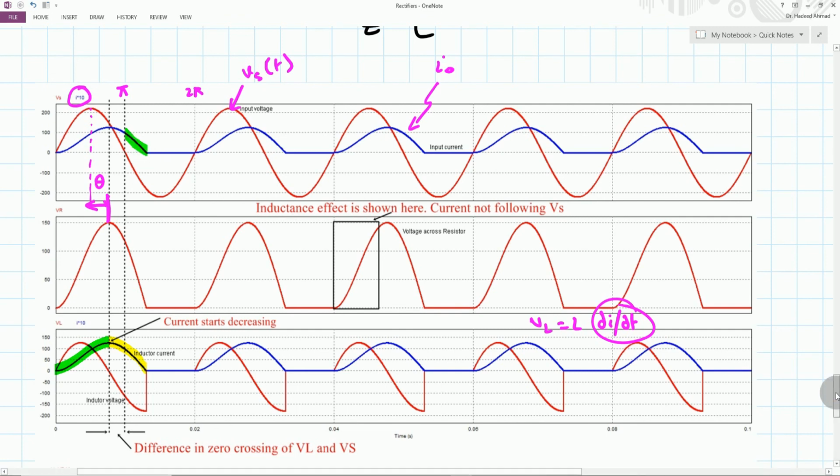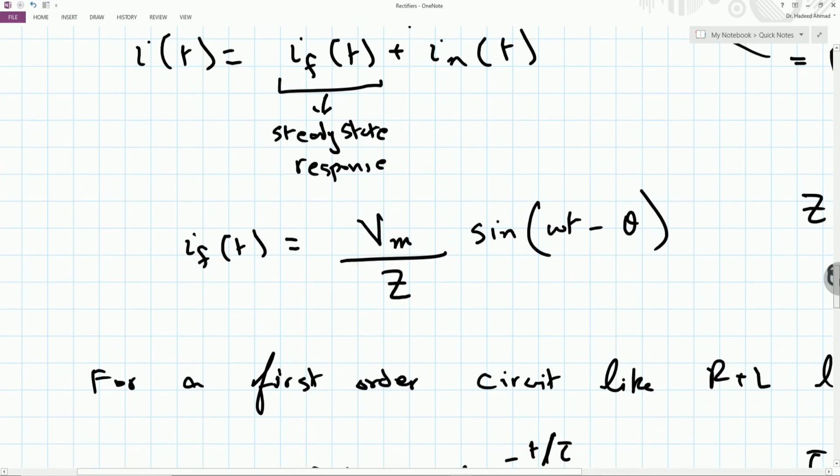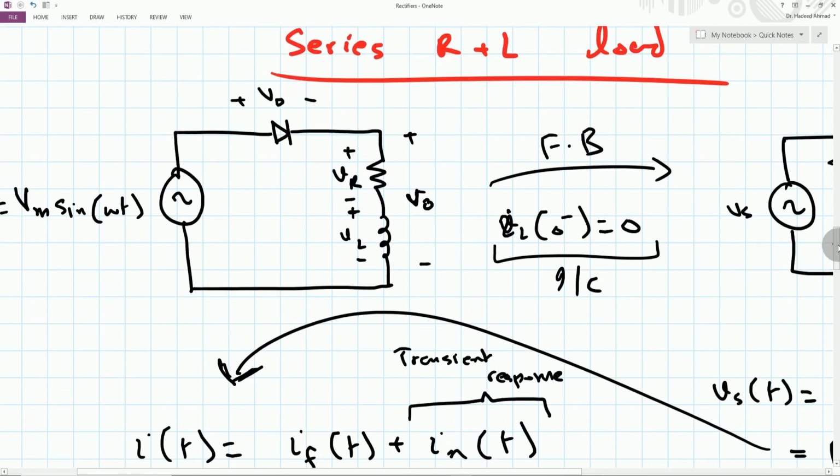We should notice one thing here, that for this particular circuit, this diode, if this is the A and this is the K, then this VAK should be greater than 0 volt for an ideal diode, and greater than 0.7 volt for a silicon diode, or 1.1 volt for a power electronic diode. Once we have this difference available, this diode will stay in the conduction mode.